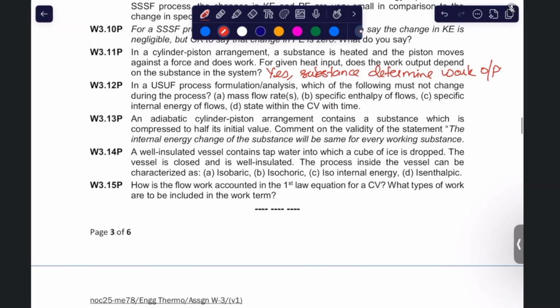At a given instant of time, at every location, the properties will be constant. But at the next instant of time, those constant properties will have a different value, though still the same throughout the spatial location. So it is not necessary that it will remain constant throughout time, but since it is written uniform, spatial variations at individual local locations will not be there.